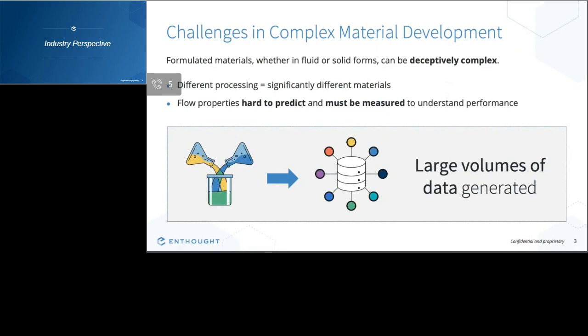One system that we faced like that was a product that required suspending microcapsules that contained oils. And what this required for the product was that these beads or capsules be stabilized and suspended for months, basically the shelf life of the product. After doing testing, this was found to be fine. For static studies, no difficulties were observed. But then when the product was transported by truck to stores, and it went over bumpy roads, when the product arrived, all of the capsules had settled out and the product was basically a failure.